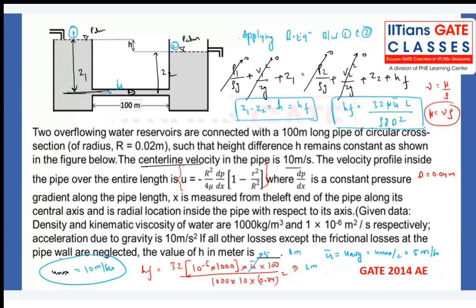And that is how you have the difference in the water level. Why is there a difference? Because of viscosity. If viscosity is zero, then both the pipes are connected, the liquid is flowing, and the liquid completely rises in that tube. There will be no water level difference, no h, small h. As you have these head losses, that's why you get the small h height, which is lesser than the previous reservoir height.